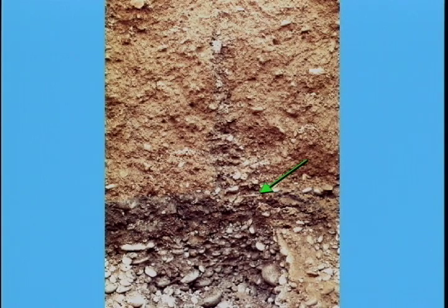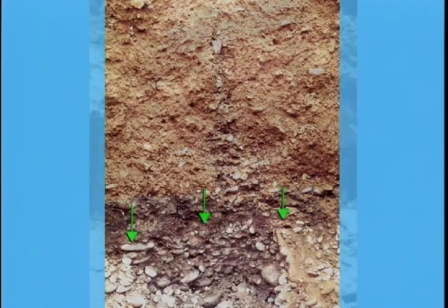A pencil was placed at the interface of the blanket and the foundation. The material along the crack is coarser than the adjacent material, presumably because some of its fine fraction has been washed out. Openwork type alluvium is evident at the bottom of the picture.